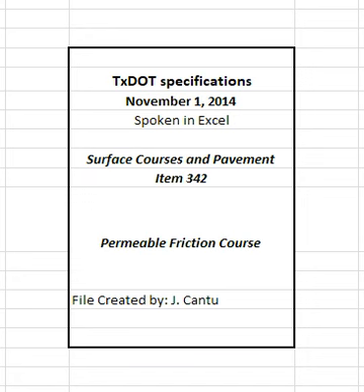4. Construction. Produce, haul, place, and compact the specified paving mixture. In addition to tests required by the specification, contractors may perform other QC tests as deemed necessary. At any time during the project, the engineer may perform production and placement tests as deemed necessary in accordance with Item 5, Control of the Work. Schedule and participate in a mandatory pre-paving meeting with the engineer on or before the first day of paving unless otherwise shown on the plans.